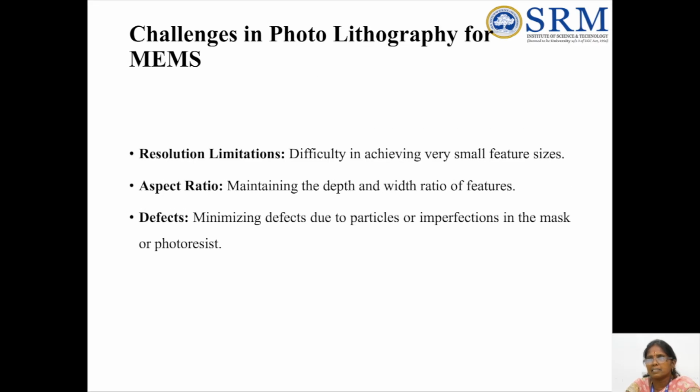What are the challenges in photolithography for MEMS? First one is resolution limitation, the difficulty in achieving very small feature sizes. Next one is aspect ratio, maintaining the ratio of depth to width of features. Next, defects, minimizing the defects due to particles or imperfections in the mask or photoresist.